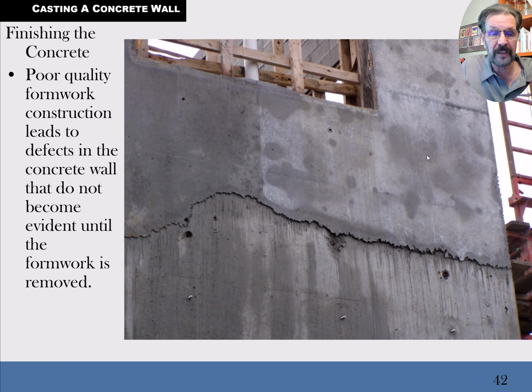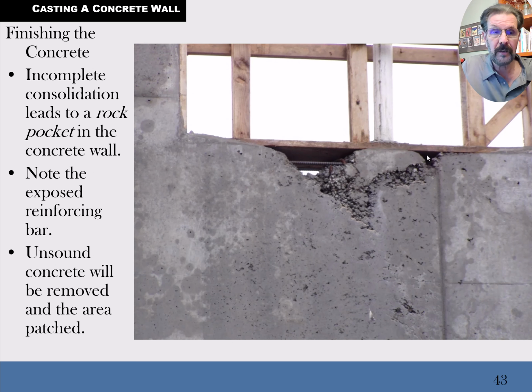So you can always hide stuff like that. But something like this is a more messed up thing. And so in something like this, we will typically install a dry pack grout in here, where we mix concrete up, basically a zero slump mix with just enough water for the chemical reaction. We can pack it in there without a concrete form, and just with rubber gloves you can pack it in and smooth it out and make it look pretty.